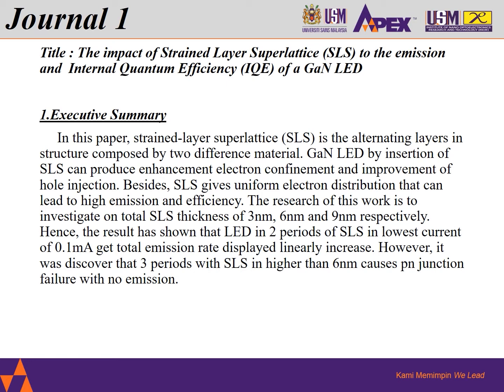In this paper, strain layer superlattice, SLS, is an alternating layer structure composed of two different materials. A GaN LED with insertion of SLS can produce enhanced electron confinement and improved hole injection. Besides, SLS gives a uniform electron distribution that can lead to high emission and efficiency.